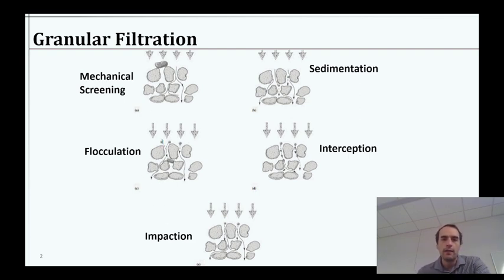So we have these individual little particles here, and as they're traveling through, they stick together and make a larger particle. So all three of those came together, met at some point, and now they're too big to carry on through, and so they'll stick to the sides. Maybe they are literally sedimenting as they're making their way through.